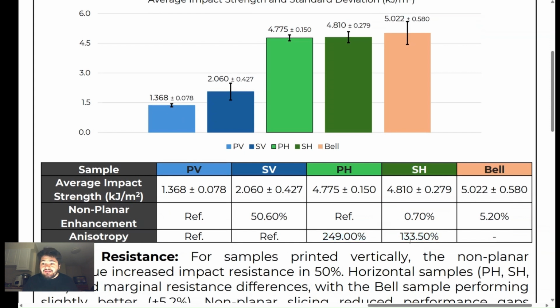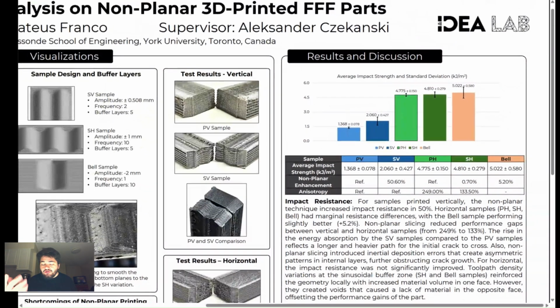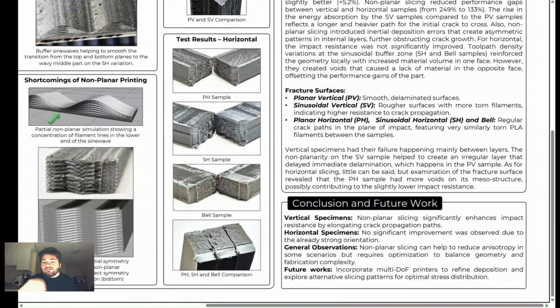So it's a very interesting result that we can take home in order to make more isotropic parts using the same machine, the same material, the same output geometry, but having a little bit more isotropy in our parts, which is good if we have a part which we don't know how it's going to be loaded when it's in use. The load is not known, because if it is known, we can optimize for it. If it's not known, it's good to have isotropy.